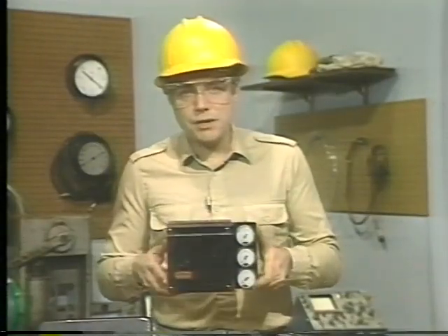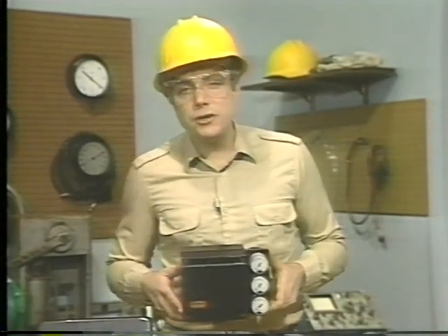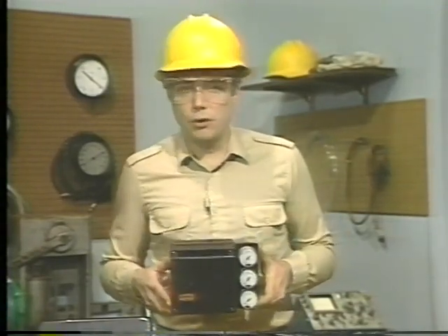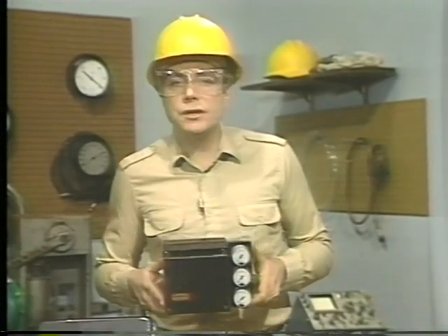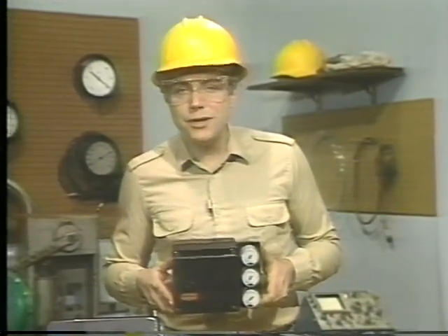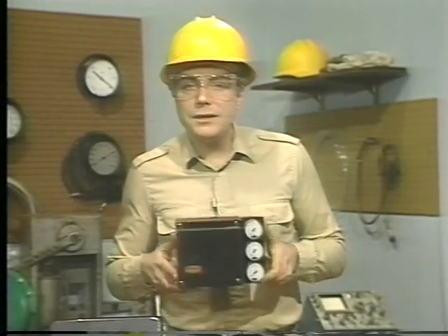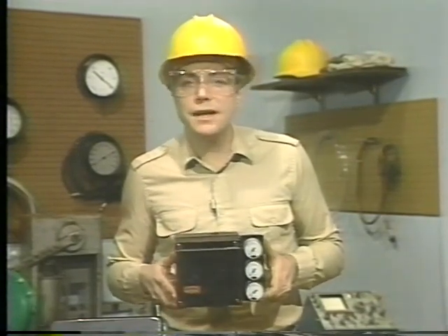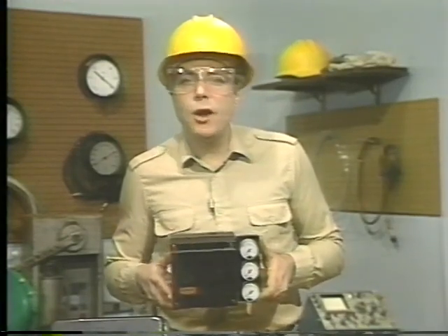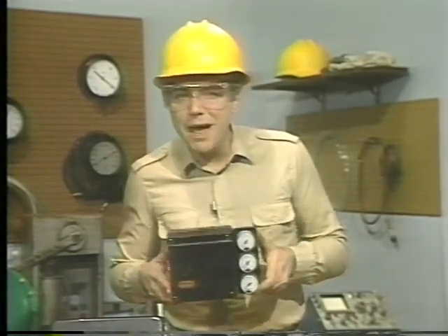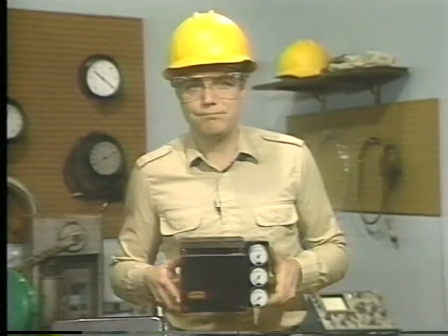So, in this positioner, balance is achieved by two opposing motions: the motion of the balance beam caused by the expansion of the bellows and the motion of the balance beam caused by the rotation of the cam. This is basically how a motion-balanced instrument works. That is, a motion balance instrument works on the principle of achieving a balance between two motions.